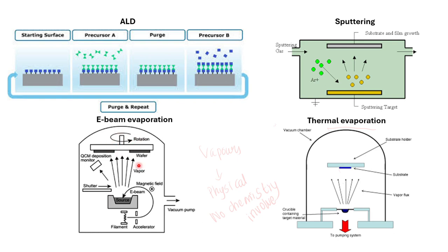In the case of thermal evaporation as well, we use a resistive heating filament to heat the crucible. Since we are heating the crucible using a resistive filament, we should make sure that our crucible has a very high melting point compared to the material that is being melted. One disadvantage of thermal evaporation is that we cannot deposit all materials, such as those with a very high melting point.